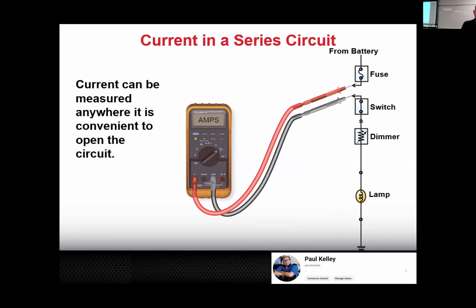And then with regard to measuring, we talked about measuring voltage, right? With regard to measuring current, remember I explained, if you want to measure current, you have to break the circuit open, send it through the meter, that's like the little toll booth, and the meter has to count the amps, and then the amps have to go through. It's very important right here that you understand you have to set your meter up to do this measurement, and I have a whole thing on DMM use, but if you have your meter set up wrong, you can have this unfused, and that's bad for the meter.